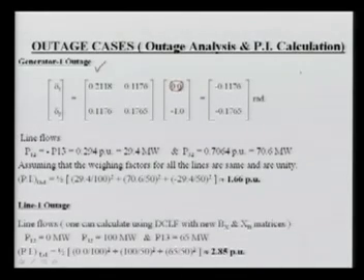Because the P, if you remember, I found P1, P2 and Pn; earlier it was 0.65. Now it is outage, meaning 0. So we have put 0, and now we are calculating delta 1 and delta 2. We are getting these values. With this, what can we calculate? Now we can calculate what the power will be. This is P1, and the 1-2 line flows. Now after the outage of this generator, we are calculating.